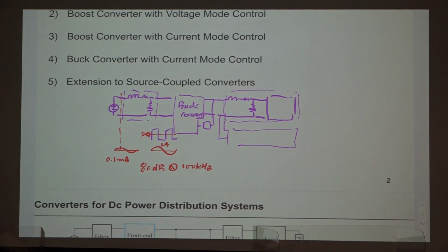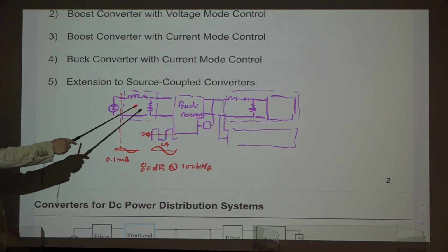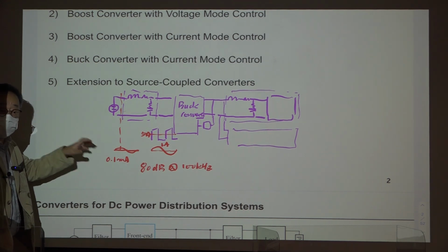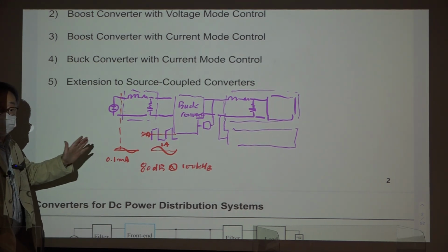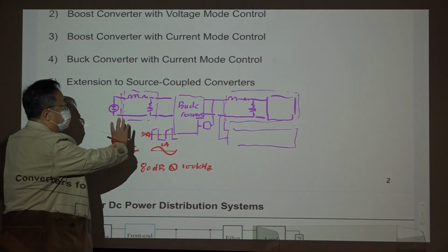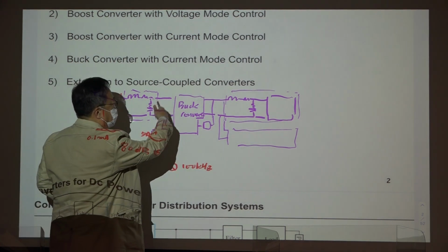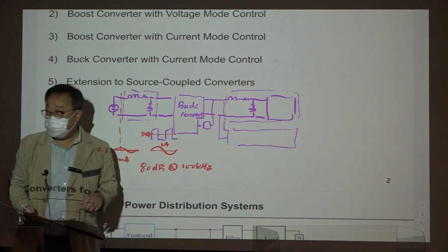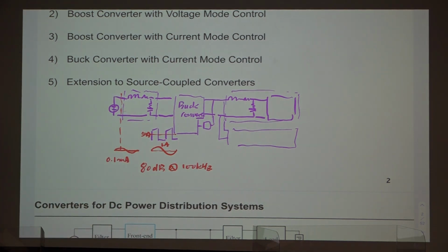Okay, if you connect this filter with -1, you are building an oscillator. That happened a lot in the past, and people suffered. And Middlebrook documented the remedy of this problem in a paper. That paper is extremely useful.